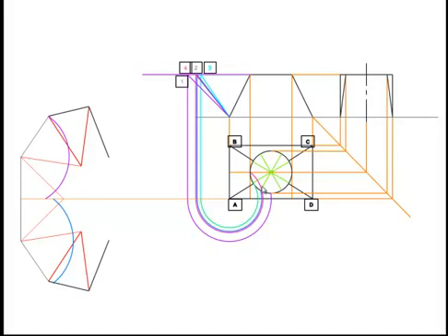Now we need to find the distance between two of these green sectional cuts and step it off from our apex here. This will locate this point where the blue line comes in contact with a circle in plan, like so.